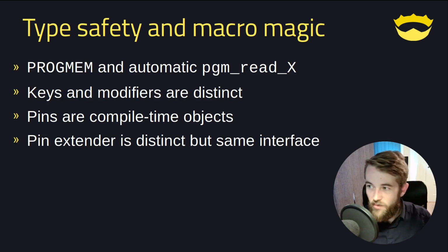And this is something you would never have run into with Arduino because you have too much overhead. But since all of the overhead was gone, I had to add a 1 tick delay. So that is sleeping for 1/80 millionth of a second, or whatever an 80 megahertz clock speed gets you for 1 tick, just to fix this issue, to let the voltage in the matrix stabilize. So that is how low overhead this system has.